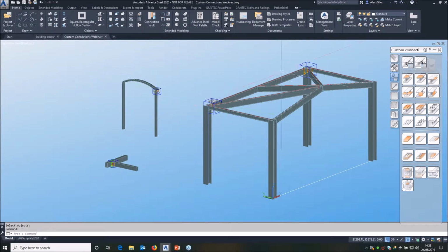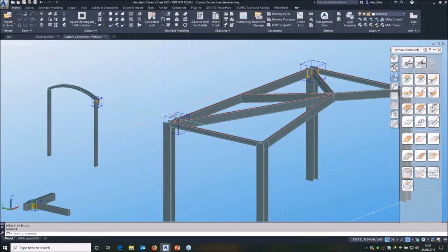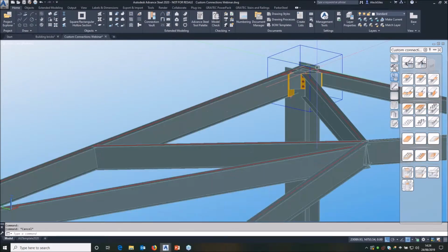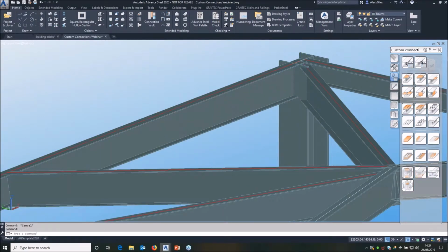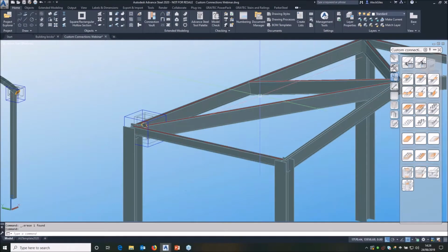So here I defined it and used it, but you can see there's no discernible difference between the two joint boxes, and that is confusing. You need to be sure you know where the definition is every time, because you need to be able to edit the definition, and you can't use joint copy and things on the definition. So you need to be careful there. In fact, I'll delete that joint over there just so there's no ambiguity.